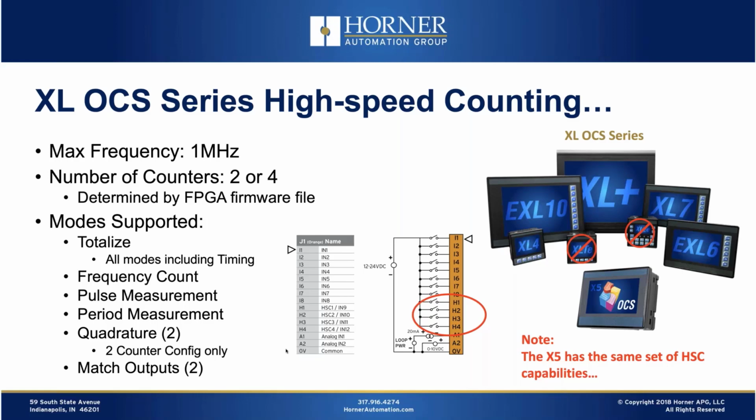We make updating firmware in the field fairly easy. You can do that from micro SD. You can do it from USB. Okay, so the modes that are supported, all modes are supported. All the examples I did were done with an XL4 in mind. So all the totalizing modes are supported. Frequency counting, pulse measurement, period measurement, 2 quadratures if you're in 2 counter mode. If you're in 4 counter mode, there's no quadrature support, so be aware of that.